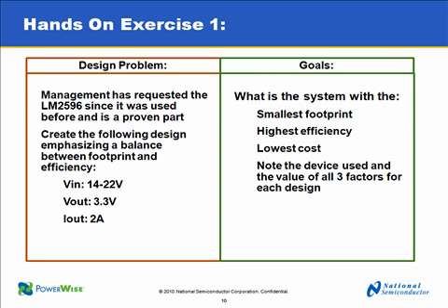And again, using the 2596 specifically, probably the easiest way to do that is to go to national.com and search for that part number. And that will take you to a panel that will let you fire up the WEBENCH design. Okay, when you're done with that, come on back to the presentation and we'll pick it up. But make sure you write down those values.